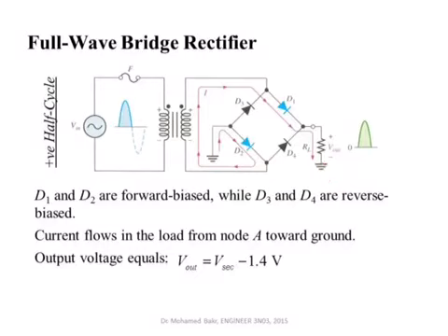Now, the very interesting part about this structure: this transformer will scale down the voltage from 120 volts, say, to 15. During the positive part of the cycle, look what's happening. This side of the secondary winding will have a positive voltage relative to this one. Okay? So this will allow current to flow in this direction and then to come back through this direction. And then the circuit is closed.